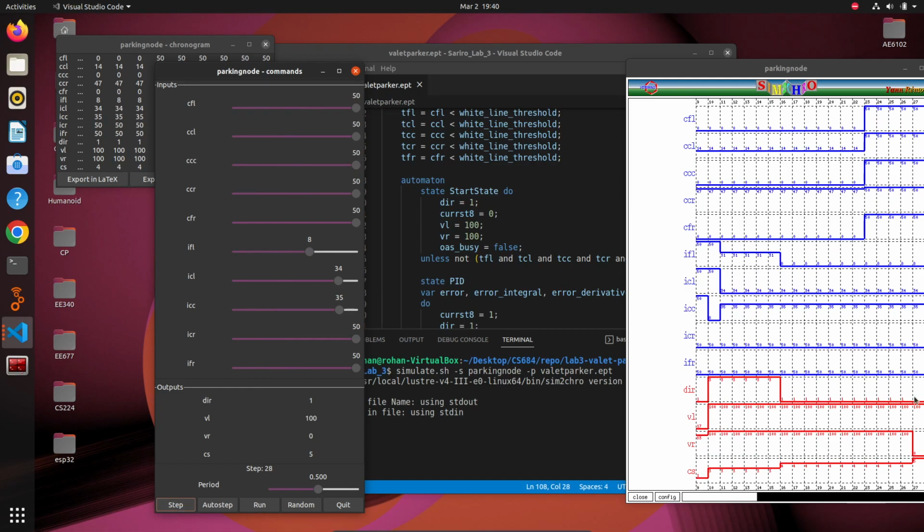So it enters state 5. In state 5 it will be doing either soft rights or soft lefts until we reach back the white line. This is like maintaining the wall distance between the far left sensor and the obstacle. If the threshold for that is 10, and the far left sensor value is less than 10, then the left motor will be high and the right motor will be low, effectively turning right.